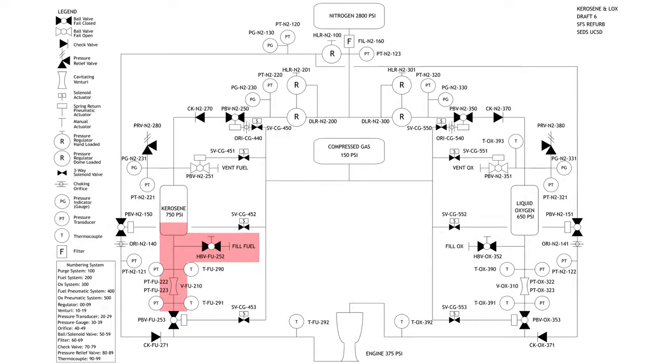And so what happens is that because liquid oxygen is cryogenic, which means it has a boiling point of like negative 300 degrees Fahrenheit, it takes a while to fill liquid oxygen because you have to chill down your whole system basically. Because our system will be running at desert temperatures, I'm not going to call it room temperature because it's definitely not 70 degrees out there, our pipes are running about 80 degrees Fahrenheit. That's almost a 400 degree difference between the liquid oxygen dewar and your pipes and your tanks. So when we put liquid oxygen through the system, as soon as it hits those tubes and pipes and tanks, it vaporizes because it boils off.